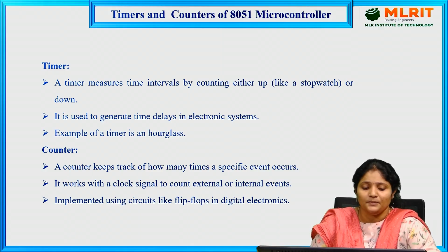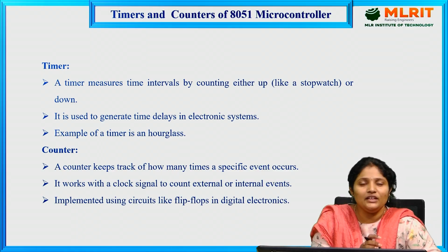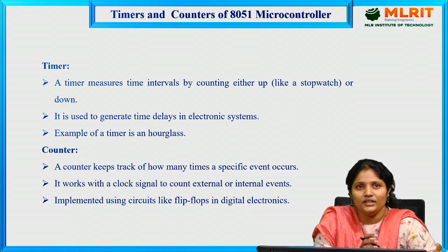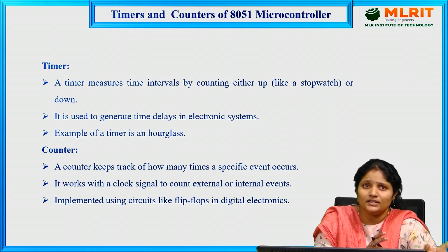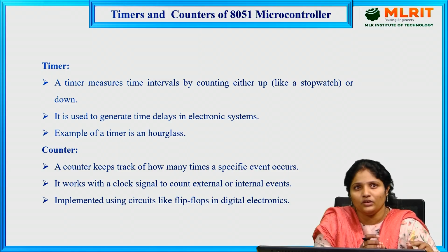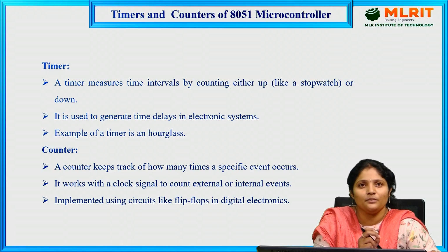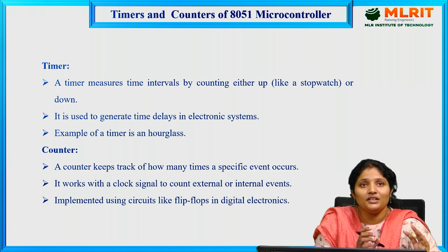In the 8051 there is one unit that can be operated as a timer and can also be operated as a counter. If we want to select that particular unit as a timer, we need to switch one single bit present in the TMOD register. It will be explained at that particular register.